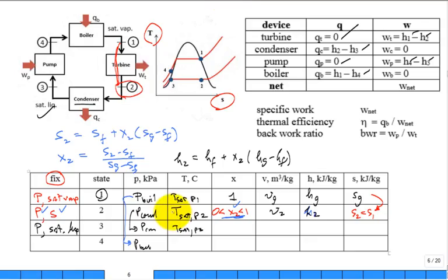Are these two temperatures the same? Hold on, it went through a heat exchanger. It went through a condenser. There's a lot of heat transfer out of that steam. You're telling me that the temperature inlet of the steam and the temperature outlet of the steam in the condenser is the same? There was a change of phase. It was constant pressure condensation, condensing it.